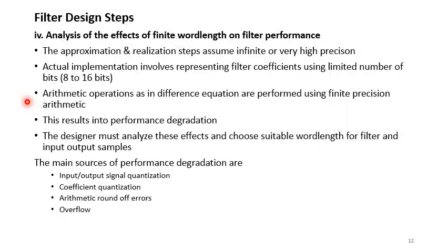The main sources of performance degradation using finite word length are, first, input-output signal quantization, because when you quantize, you have quantization noise which is irreversible. So here we'll have some degradation.